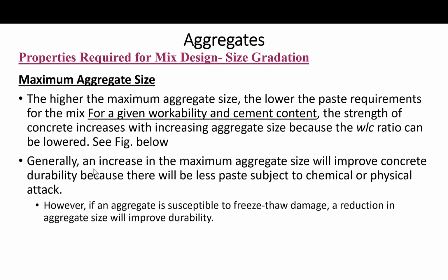Remember, I made this statement before. There will be less paste subject to chemical or physical attack. But if an aggregate is, for example, susceptible to freeze-thaw damage, a reduction in aggregate size will improve durability, as we may see in the durability discussion.